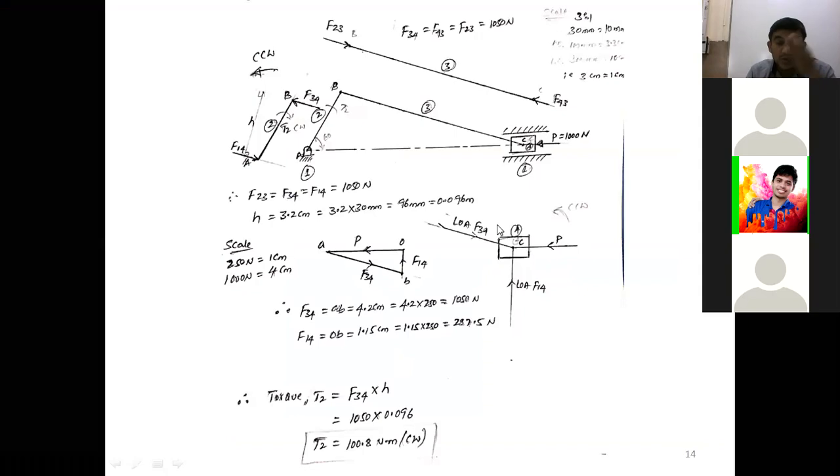Okay, now we consider link 4, because on link 4 the applied force is known in both magnitude and direction. We know that external applied force, both magnitude and direction, that's why we consider link 4. On link 4, draw the free body diagram of the slider. In a freehand sketch, draw a rectangular box. In the middle of the box, draw a horizontal line. On the horizontal line, an external force P is applied. We know the direction, right? This is the line of action of the external applied force on the body.